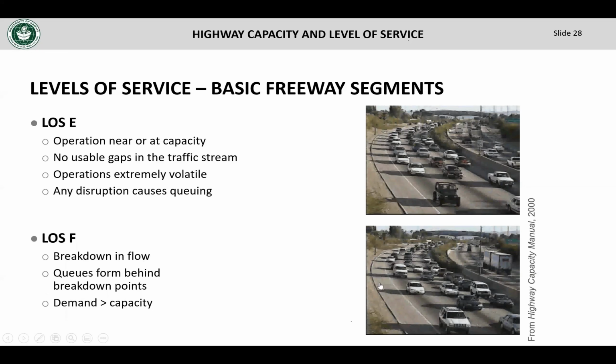And then you have level of service F, where there's a breakdown in traffic flow. Level of service F represents really when you have a higher demand than can pass through the section. And if you want a good example of how that can occur, during significant portions of the day on H1, when you have the H1 and H2 merge, let's say coming to town immediately after the tunnel, you have 3 lanes coming on H201, and you have 2 lanes from H1 joining. So those are 5 lanes, and then those become, I think now it's 4 lanes immediately downstream.